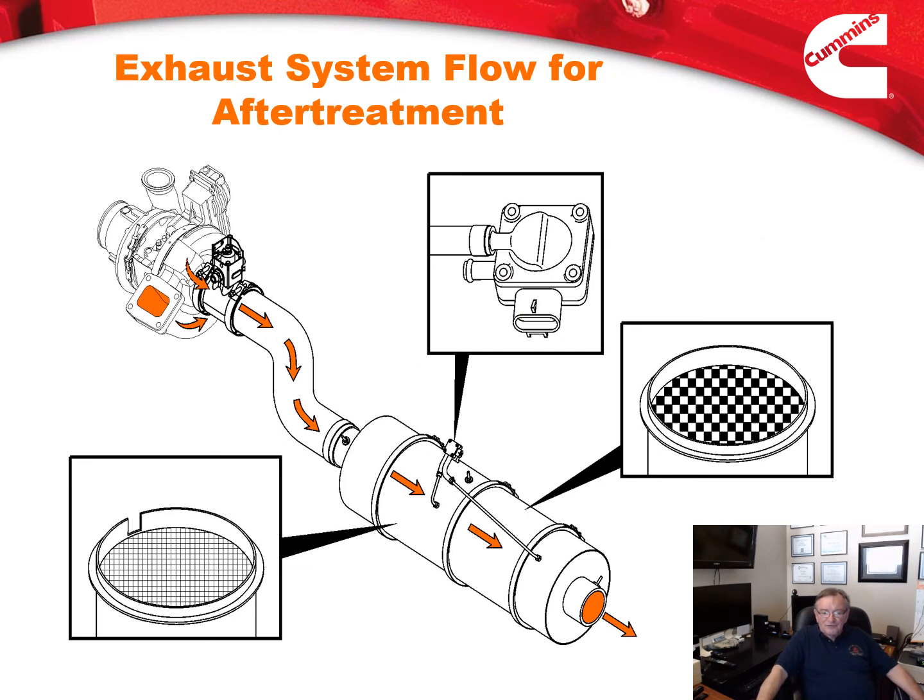Here's a simplified look at the exhaust flowing through from the turbo. It's entering the diesel oxidizing catalyst and the diesel particulate filter, and on engines from 2010, it travels on to the SCR, selective catalytic reduction chamber, which is next.